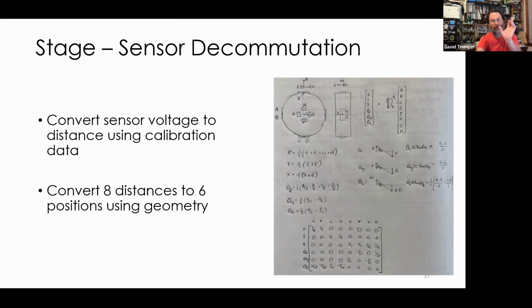If you're doing spacecraft attitude control, you've got to get into the real thing. If you have large angles, you've got to get into coordinate frames and how you define them in a unique way, and do you use Euler angles or quaternions or such. But for these little tilt things, a linear transformation decouples. Right. Okay, thanks.